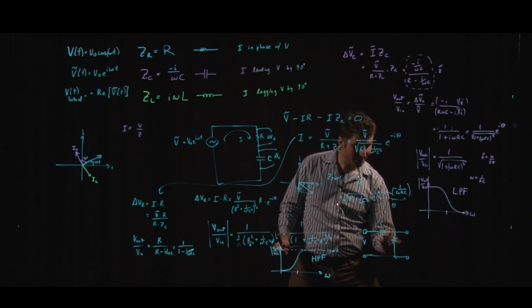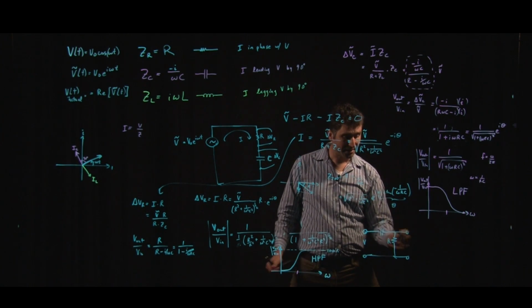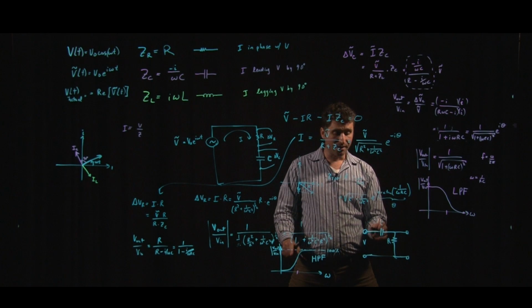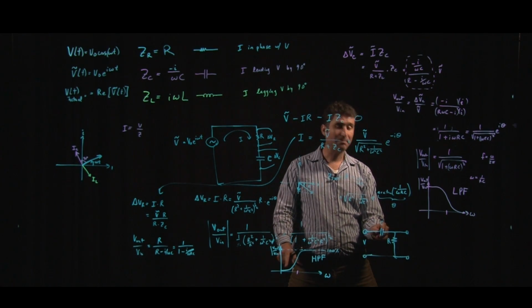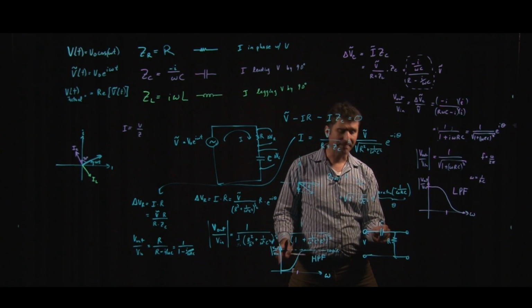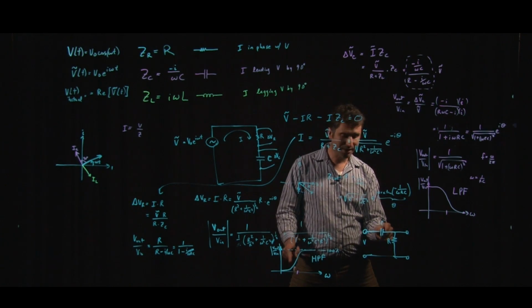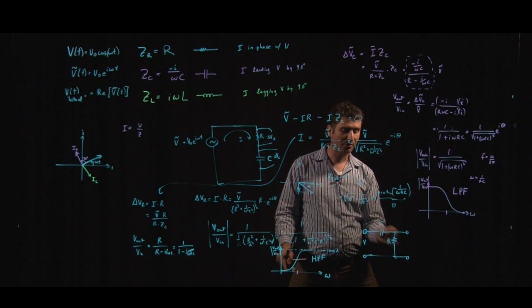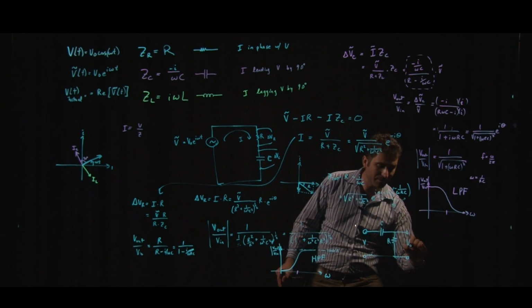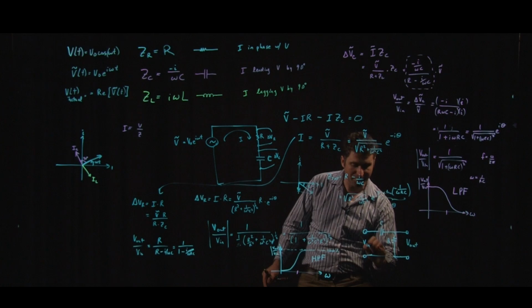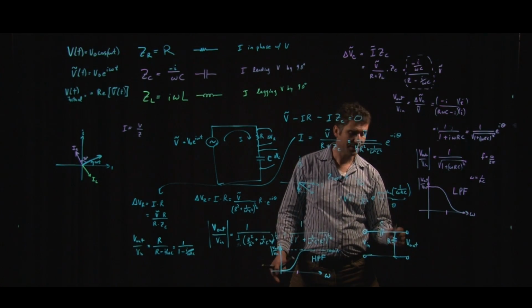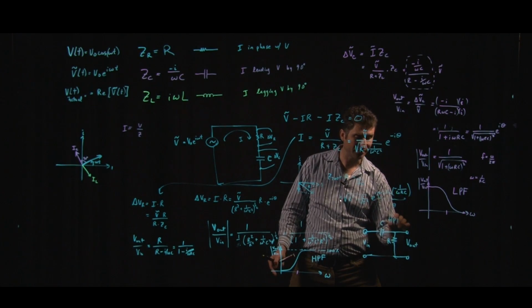So we have a capacitor and we have a resistor, and in this case, you can think of it as that for low frequencies, current is blocked essentially by the capacitor. And so only high frequencies are able to charge and discharge this capacitor more quickly. And so the voltage that is measured out here, compared with the voltage that's measured in, only passes the high frequency components. So this is called a high pass filter.